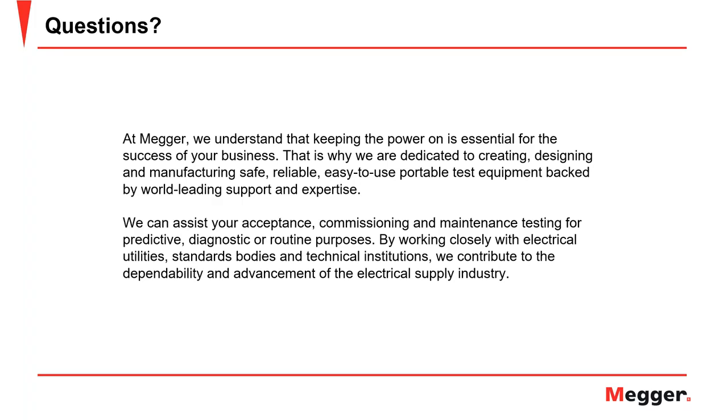Maybe it's a good idea to, because your CTs are the eyes that you have into the operation of the motor, both CTs and PTs in the cases where you're operating with motors whose voltage level requires you to use potential transformers as well. Those are your eyes into the operation of the motors, and your protections are only going to be as good as your primary transducers, which are the CTs and PTs. Okay, I'd say that's the answer. All right, thanks a lot.